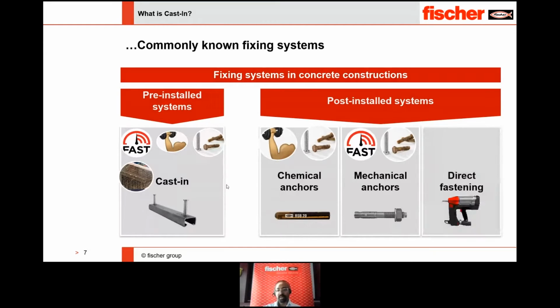And the third type is the direct fastening option, which is some sort of shooting arrangement using gas or powder actuated system. You shoot some fastening elements into the concrete. So this is extremely fast, but then you don't get heavy duty performance, or you cannot have multiple options. So the main advantage you have is that it is fast. That's it.